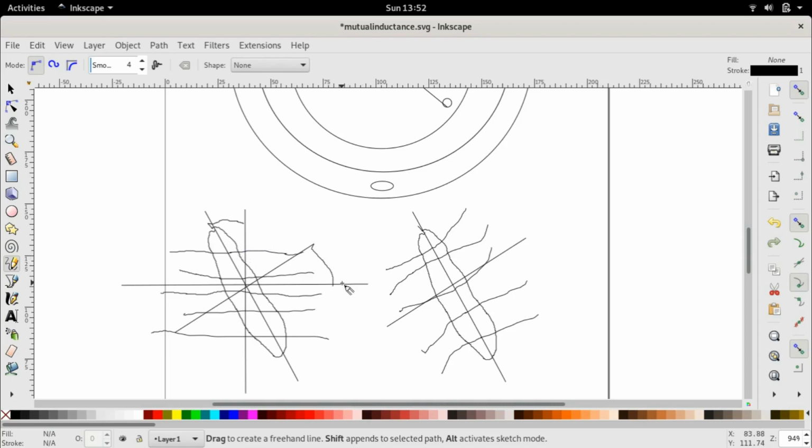And quite obviously, if we take a projection of the stator flux with respect to this theoretical rotor flux, then that new projected stator flux will be the flux that completely links with the rotor.